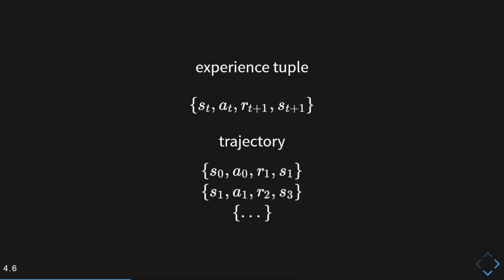And as I mentioned before, there will be some interaction between your agent and your environment, so your Python program and your CFD code. With every interaction, you will generate something called the experience tuple, which is simply the tuple of the state, the action that you took, the reward that you received, and the state that you transition into. Now, doing this a bunch of times, you generate something called the trajectory, which is just an accumulation of the pressure probe values, the actuation that you took, so the angular velocity, for example, and then the rewards, computed from the force coefficients.